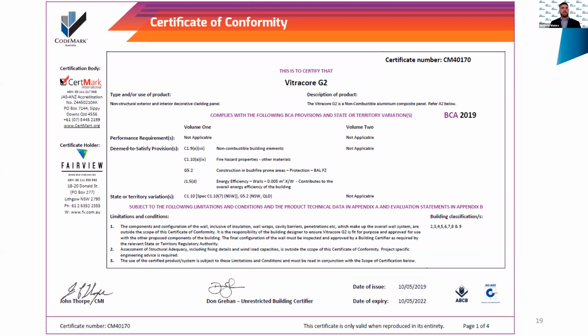We've also received some comments around how a building surveyor isn't permitted to refuse to approve building work if it complies with the certificate of accreditation. This applies to BRAC certificates and code mark certificates. Now, in the situations that we're seeing in building auditing, often the building work doesn't comply with the accreditation. Either it's used outside the limitations, or there are other relevant provisions that aren't addressed in the certificate that aren't considered anywhere in the permit documentation. So it's really important for building surveyors to understand the limitations with the certificates and ensure they're used appropriately and not accepted in blind faith as satisfying every aspect of the code.